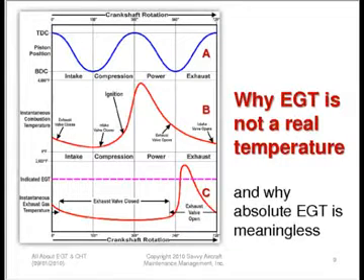and it's basically seeing nothing particularly interesting during about 2/3 of the cycle, 2/3 of the time. Then, when the exhaust valve finally starts to open during the exhaust stroke, all of a sudden the EGT probe starts seeing some real interesting stuff. And what does it see?